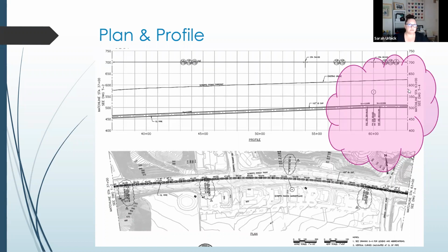Pay attention to the scales, right? So down below, our horizontal scale is 1 to 100. Our vertical scale is 1 to 50. Here, this is 100 feet. That looks like a lot bigger than 1 inch. So our vertical scales, our profile scales are different as well, vertical to horizontal. Okay. Watch out for the scales. That will bite you at some point, hopefully not too badly. All right. So we have our existing grade and we have an item here.